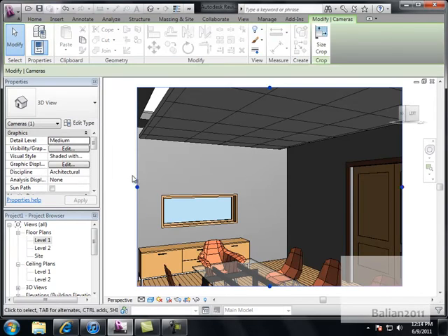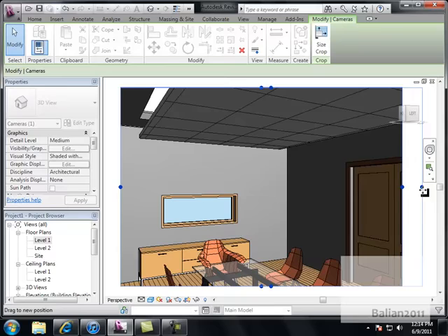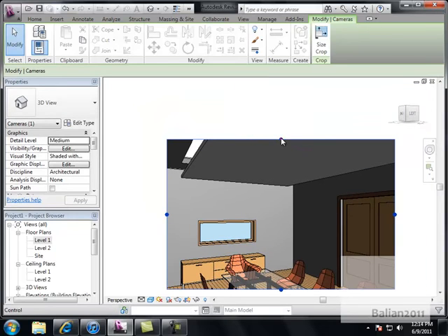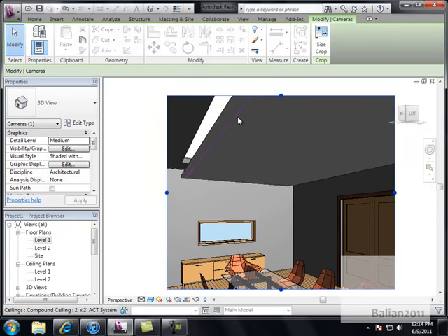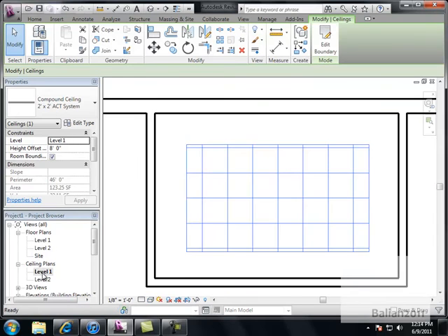Shaded. Click on the outer edge to expand. Hey, look, guys. This part here actually did the opposite. Look at this. This ceiling is lower than that. So I want to reverse that, right? So I'll go to level 1. Highlight this. Oh, that's at 8 feet. My apologies. This should be maybe 9'6".